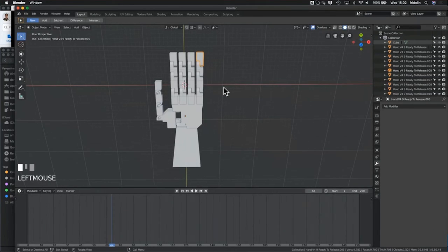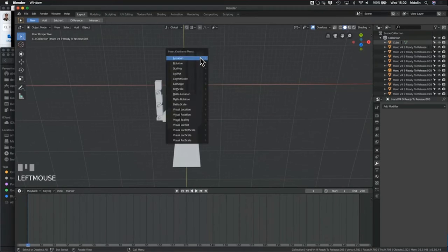But we're not animating anything. Nothing's moving, so moving along the timeline is really boring, as nothing at all is happening. However, if we insert a keyframe, and I do that up here in the 3D window by pressing the I key with, say, this thing selected, there's a bunch of different properties.